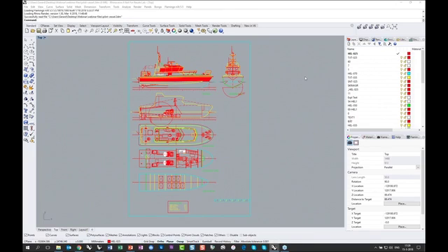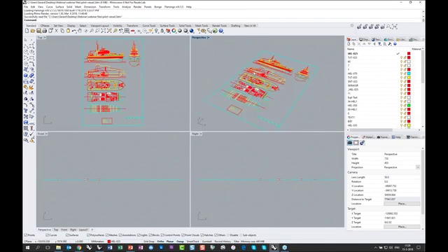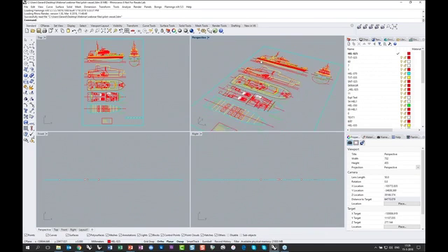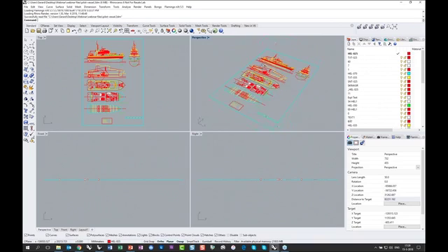In the past, I simply opened an AutoCAD drawing in Rhino and started modeling 3D geometry in that. But often AutoCAD drawings are polluted with blocks, with many layers, hatches, etc. And then I quickly deleted a lot of information in that AutoCAD drawing. And then at a later time, I had no idea which version I actually used to create my 3D material. So what we see here is a 2D general arrangement plan that you are probably familiar with in your business.